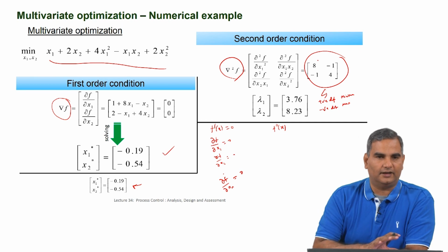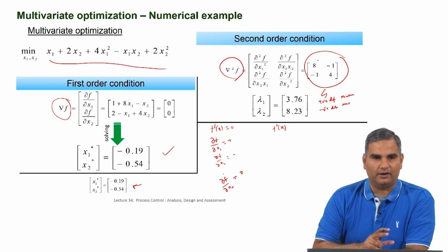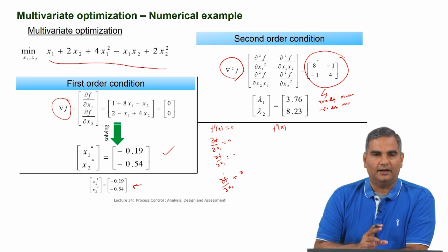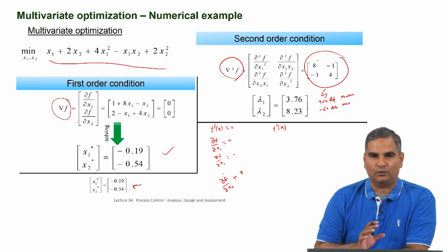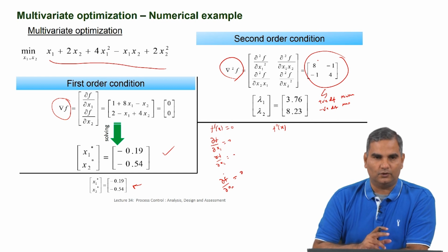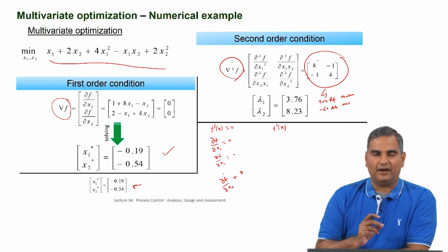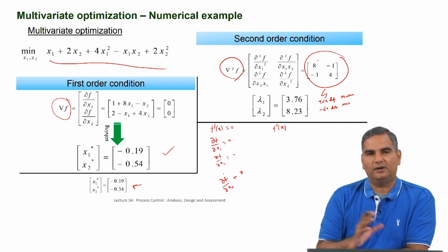This is an important idea, and let me make the connection again. The reason we are interested in multiple variables is that when I am making a move plan, I have variables u_{k+1} all the way up to u_{k+m-1}. Though they all represent the same control input, these are values the control input will take at different points. So, I am going to think of them as separate variables, and then formulate an optimization problem based on these variables.